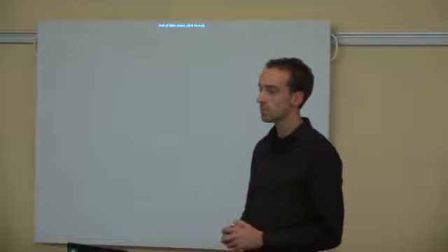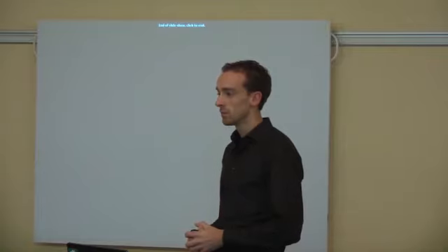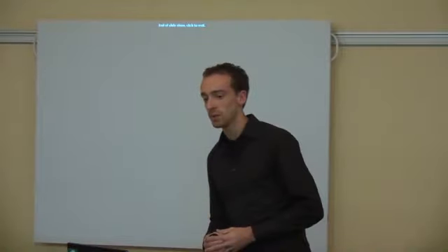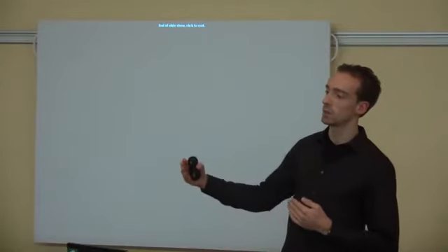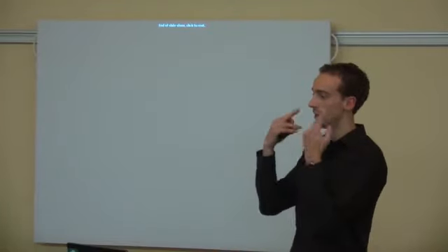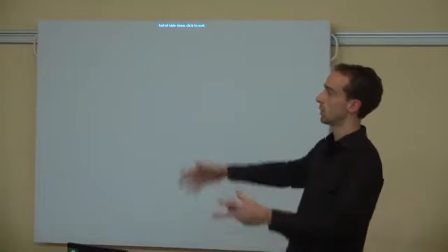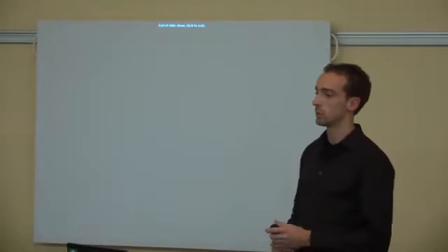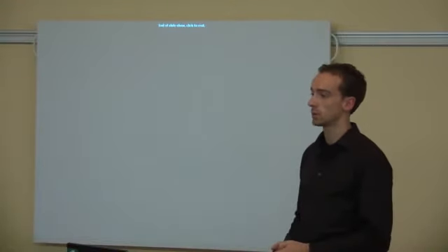So also the Kinect sensor, what is its role? Because if you look at how we detect the ball using the camera, it's still needed. It is still needed because the beneficial thing of the Kinect camera is that it also has a depth image, so it's pretty robust for balls. If a referee is walking by who has a slightly yellow face, the front camera doesn't really notice if it's a ball or not. And if there's a really big yellow thing on the ceiling or on the side of the field, the front camera can give a lot of false positives because it doesn't have this depth information. So we first rely on the Kinect sensor, and after that comes this camera system.